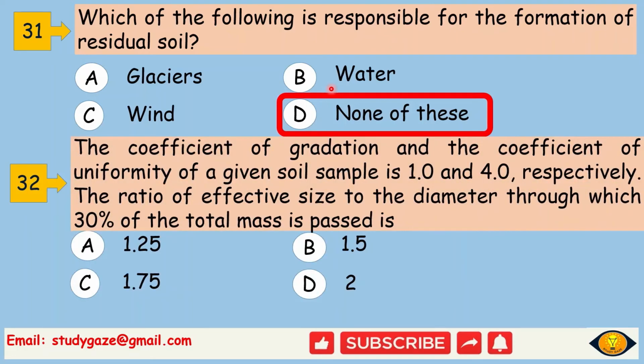Next, the coefficient of gradation and the coefficient of uniformity of a given soil sample are 1 and 4 respectively. The ratio of the diameter through which 30% of the total mass passes to the effective size is. So you have to calculate the ratio of d30 to the effective size.